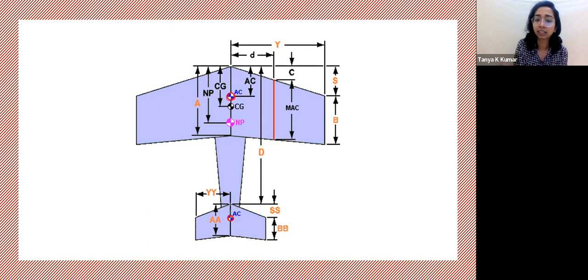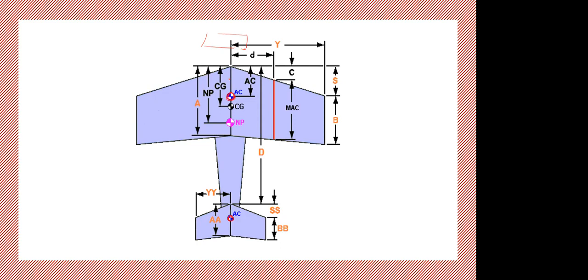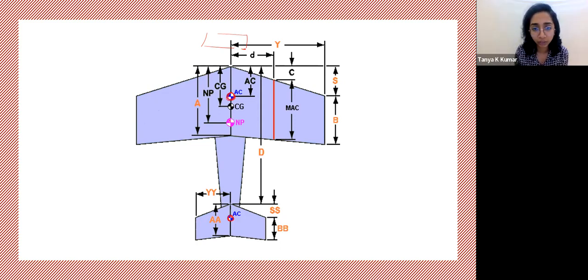Now, like he said, the canard is just like a tail, but it's added ahead. So it'll be ahead in the fuselage reference line. This will be your canard. If you have an aerodynamic component that is added ahead of your wing, will the neutral point shift forward or backward? When I added a tail, it shifted backwards. When I added a canard, where will it shift? Ahead, exactly. So your neutral point will shift ahead.